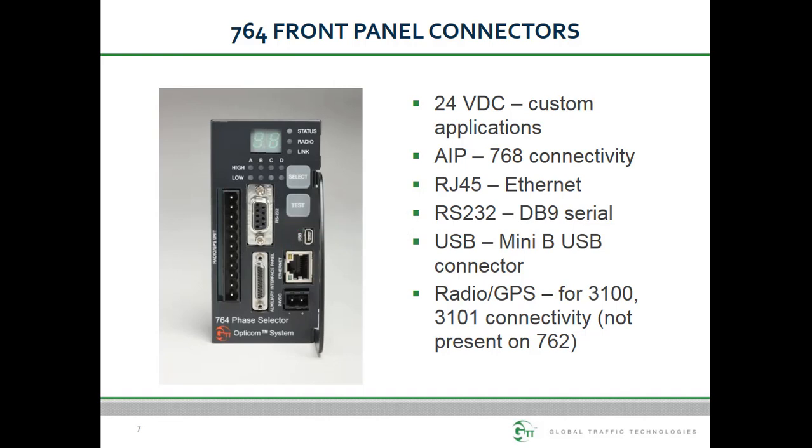The default baud rate is 115,200. And finally, there's the USB port. This is an alternative port to use when communicating with OnSite locally. It uses a Mini B USB connector. It is recommended that you use the RS-232 port, but USB is an option. When you first plug into this port, a driver will be installed on your PC, which will then create a serial port for OnSite to use.